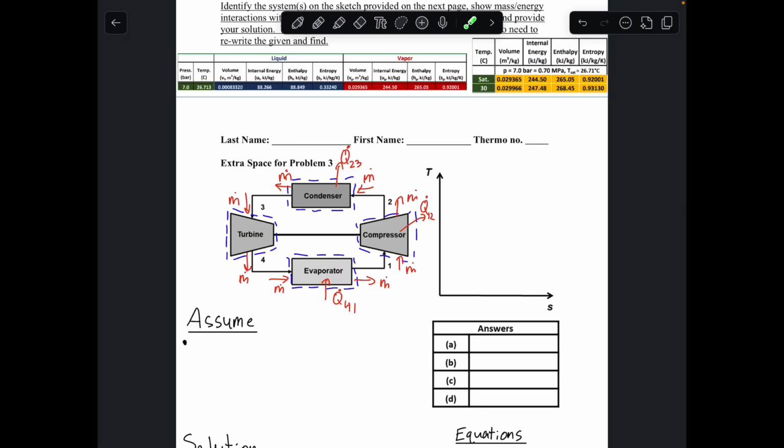So in order to do that, we need to put some work into our compressor to make the system run, but that's the goal of the evaporator, is to remove heat from that cold reservoir, and the goal of the condenser is to reject that heat out to a hot reservoir. Then for our work terms, since we don't have any pressure drops across these components, we usually consider condensers and evaporators as no work devices, so we don't have to worry about work for either of these.